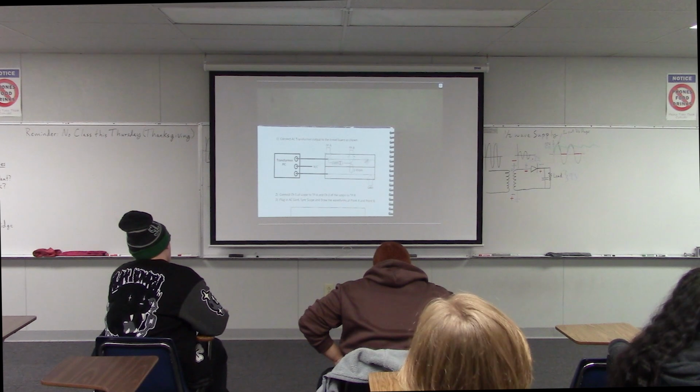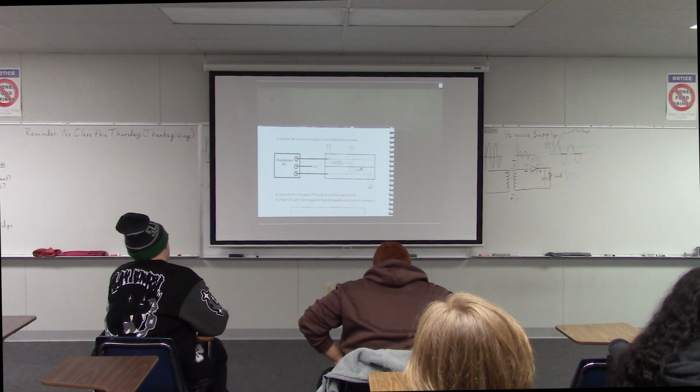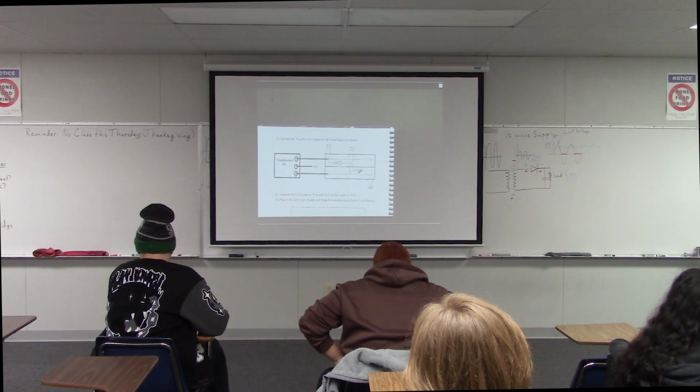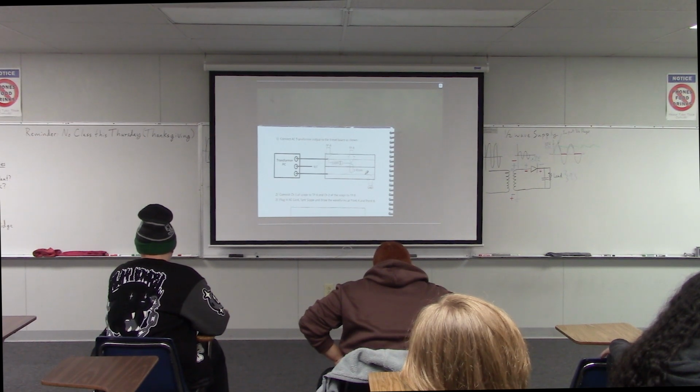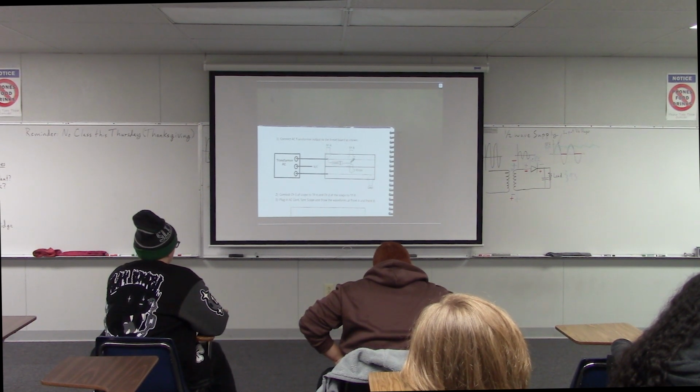The place that you would put the capacitor is in parallel with this load, in other words, next to this resistor. And the negative side of the capacitor is going to go into ground down here. Okay? So that's how you know which way to plug in the capacitor. The negative side goes to ground. And then the positive side would go to the top of the resistor.